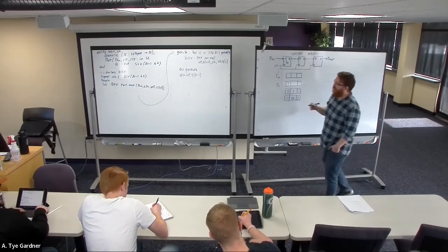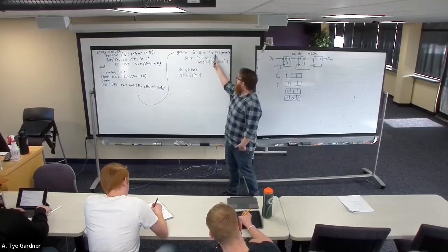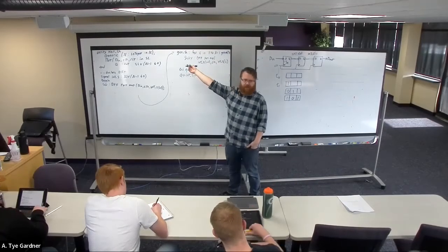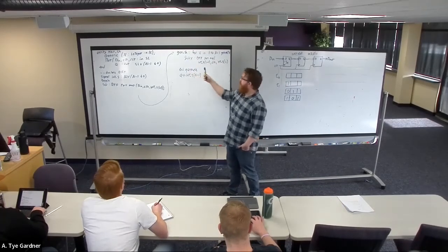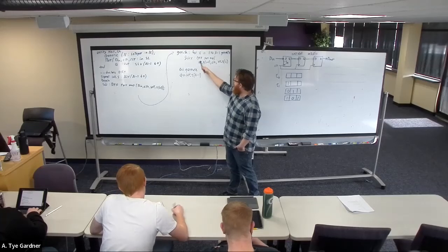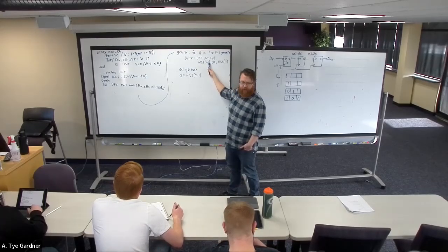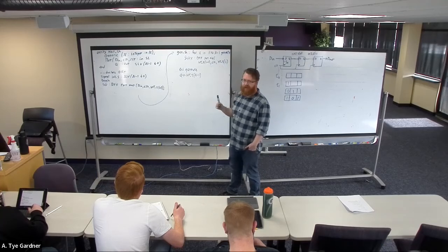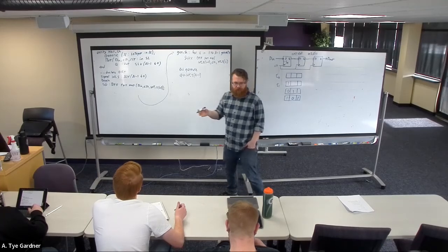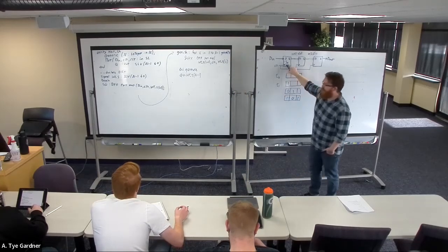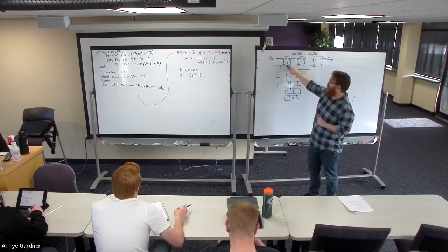Okay, so what this does is for however many I told it to be, default is 16, it's going to build a D flip-flop and attach the index I minus 1 at the input and I at the output. So for the first generate, I've built this one manually, right? That's the last row in the first column.